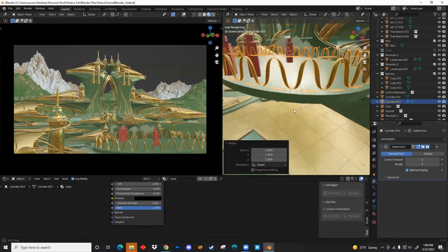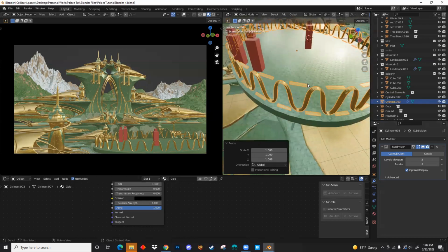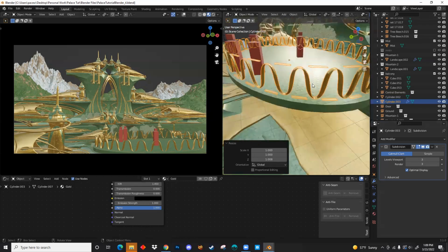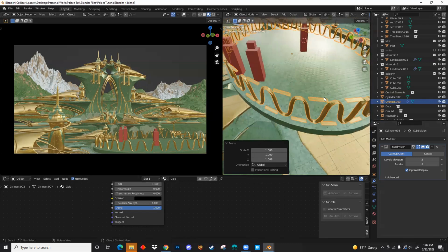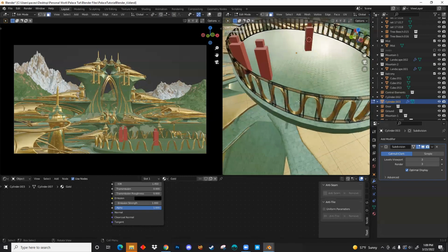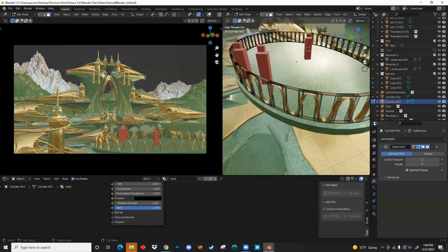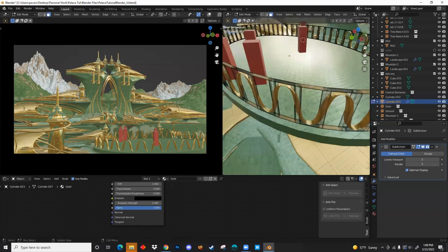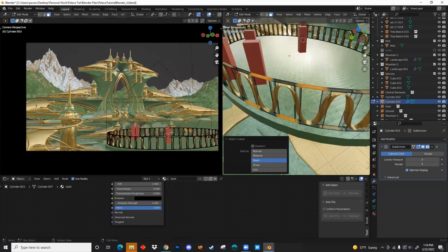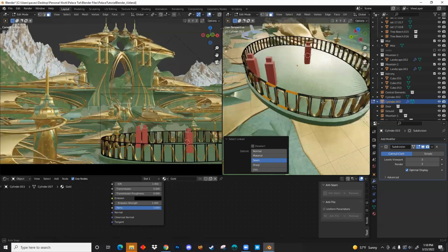And I think what we should try is just deleting these in-between areas. I don't think they make sense here, and we can always just create another round shape. So let's do that real quick. If we just tab into edit mode, we'll actually see the original shape as a wireframe around the flowing shape. So all I need to do in order to delete those in-between areas is hover over them and hit the L key. And let's just check what we're doing here.